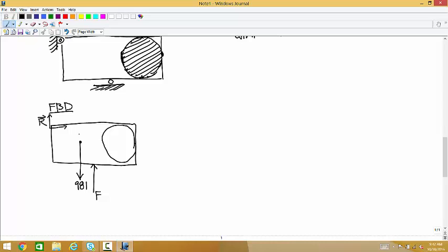One thing that's a useful thing to keep in mind, and it's going to come up more when we talk about distributed loads, is weight is always acting down. And if our components have the y-axis vertical, which one of the 2 centroid components is useful and which one is useless for applying the weight force?